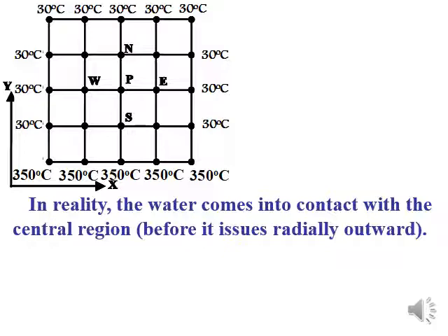So this point will be subjected to the strongest convection effect, especially when water changes its direction, so that it significantly impinges on the surface and changes severely its direction by 90 degrees, so that there is a severe strain on the fluid when it changes its direction. And of course my cooling capacity is stronger whenever I hit the surface face to face, so that I have the strongest capacity of water cooling.